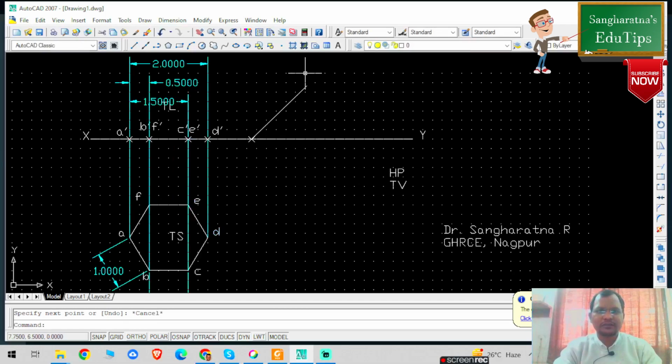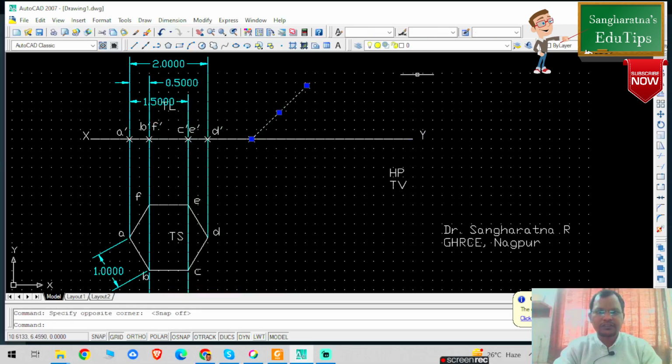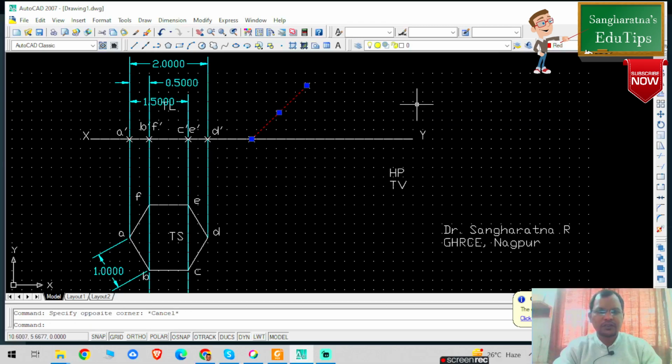Okay, now you can check, basically this is my another point D dash. If it is not mapping, you can click on O snap. Okay, so immediately. Now I am converting this particular line. Okay, so I'm clicking on snap. What I'm going to do is click on this line and convert it into red color, because you will come to know why now.